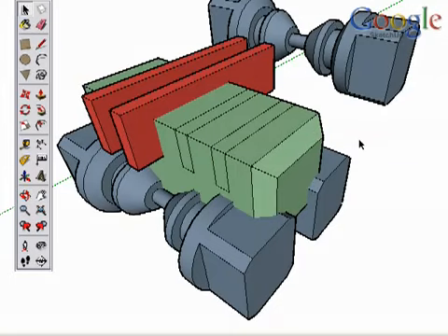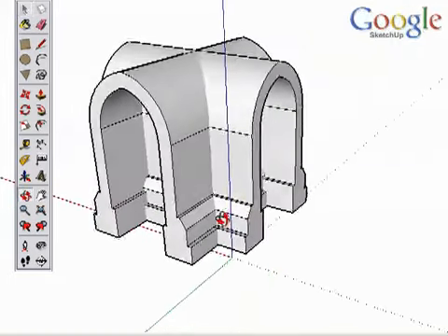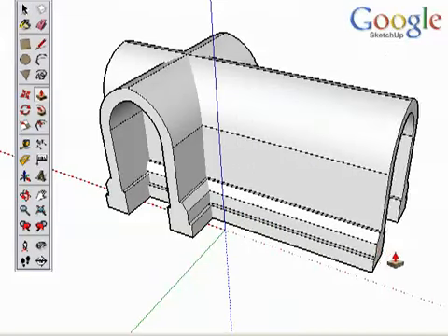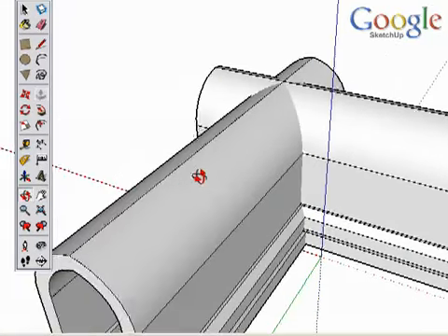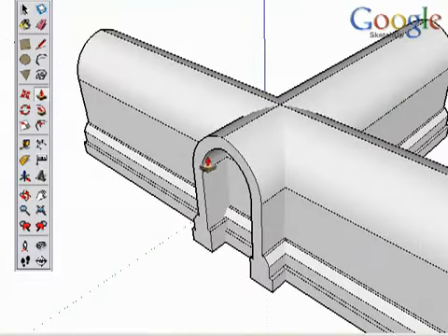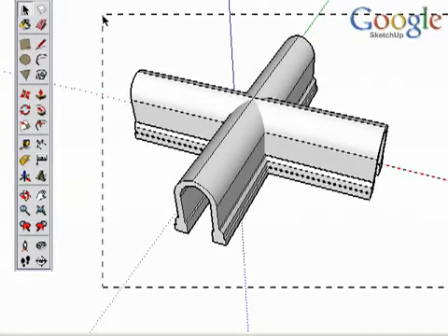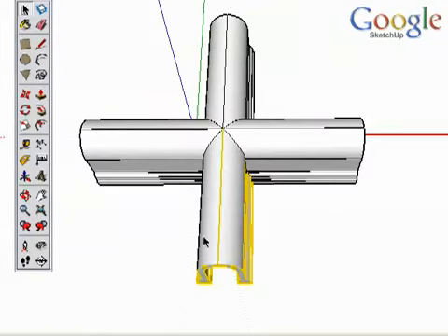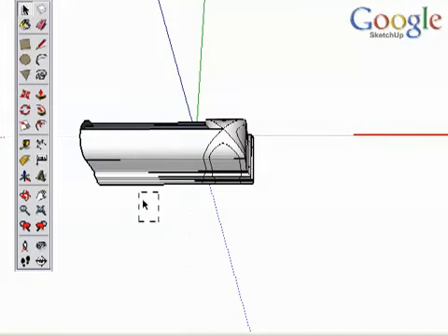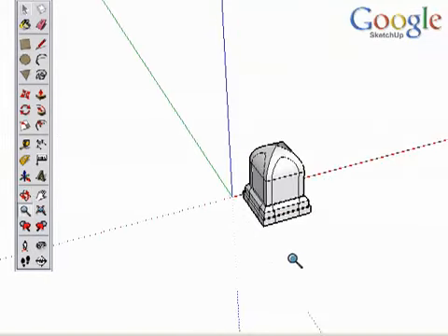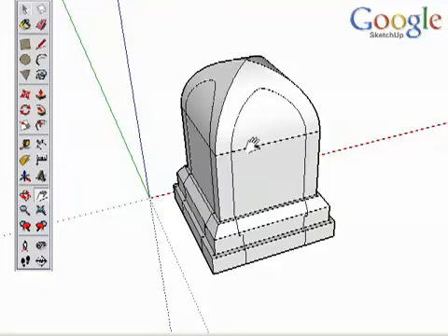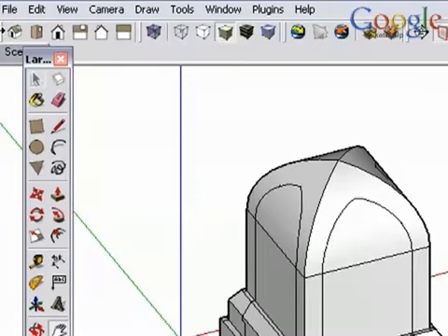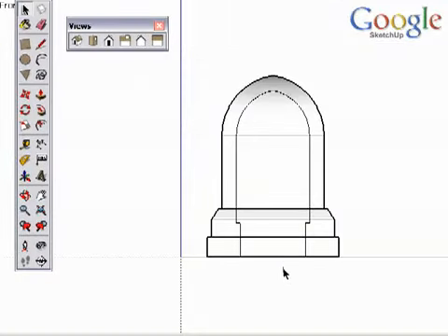Now that you understand the ways to intersect a model, let's look at some tips to make you more effective. One of the most common tasks when intersecting is to be able to clean up the intersection afterwards. It often helps to make the intersecting shape much longer than it needs to be, thus making it easy to select and delete. It also helps at times to toggle perspective off and choose an orthographic view to select and delete intersected geometry.